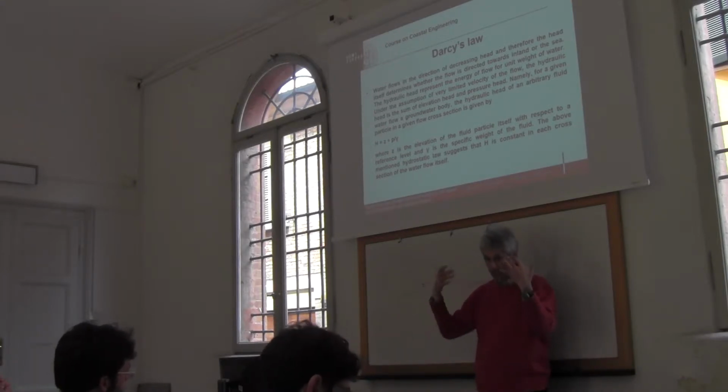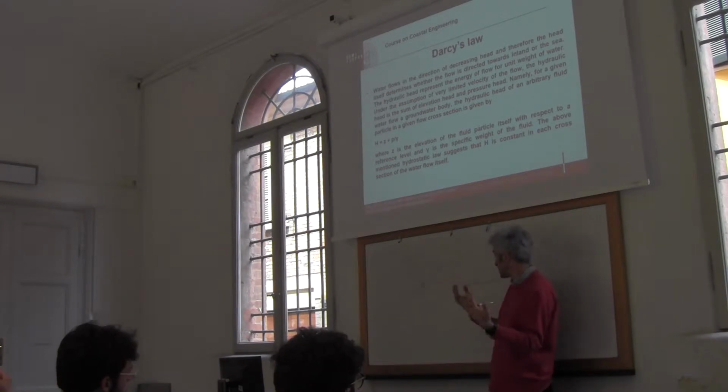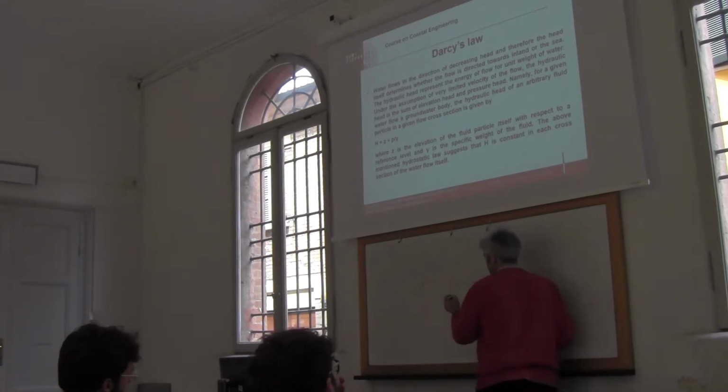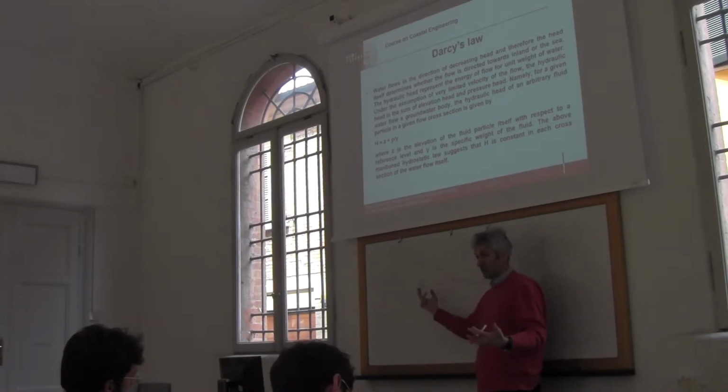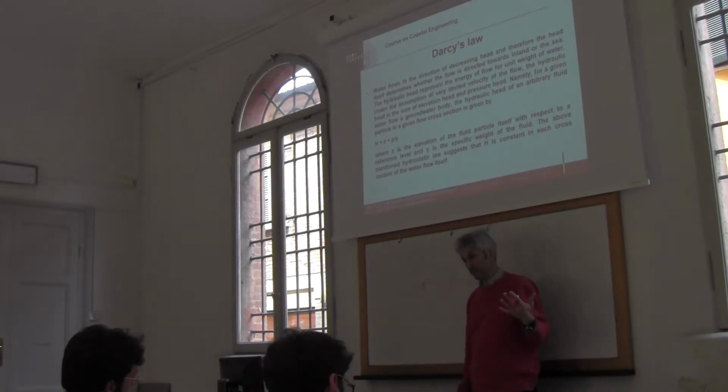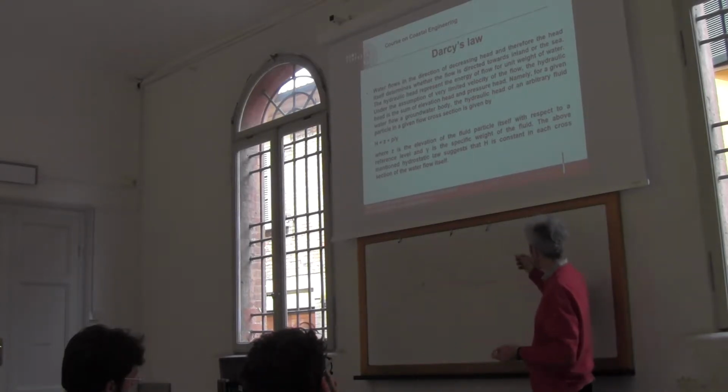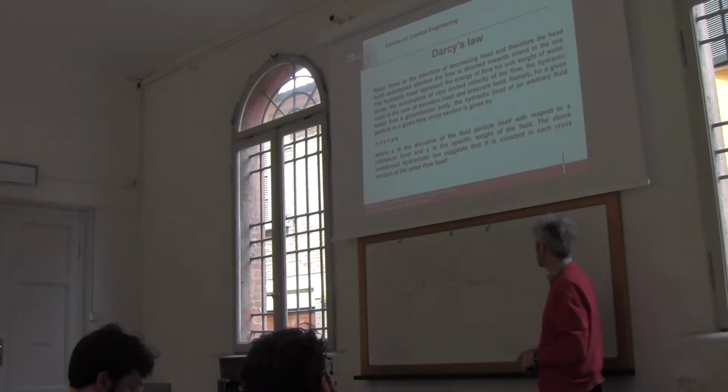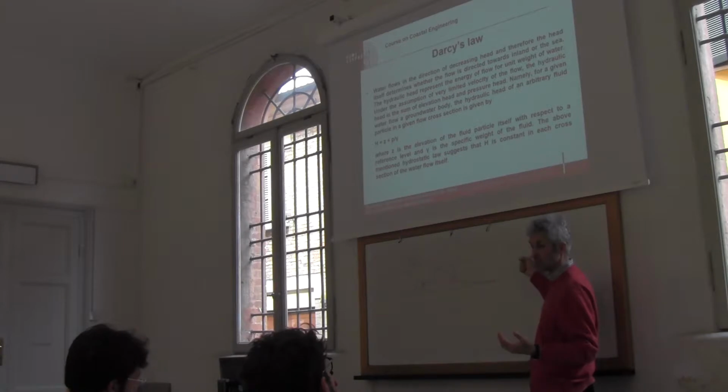So we can assume that the pressure that is given here is the same pressure that is given on a water particle that is placed here, because there is no dissipation of pressure through the medium. And therefore the pressure is given by gamma S times H. This is for the hydrostatic law.